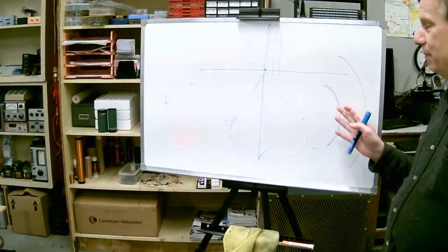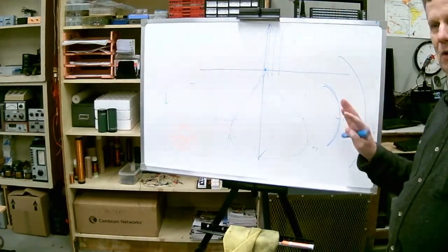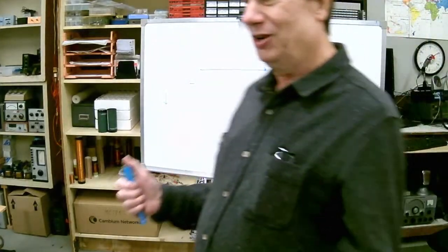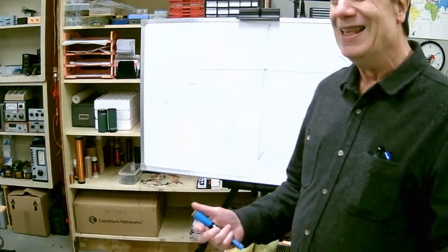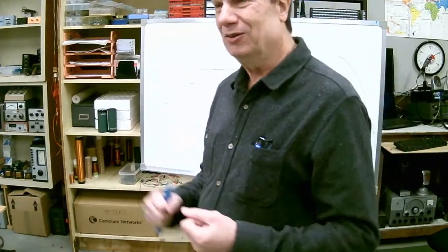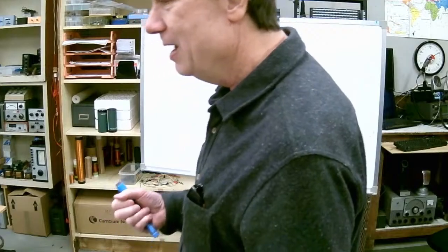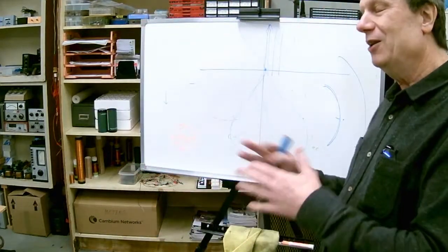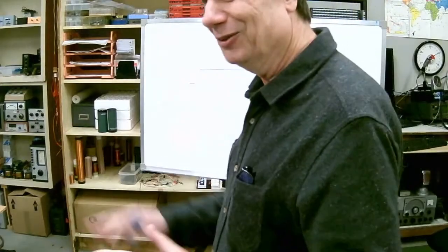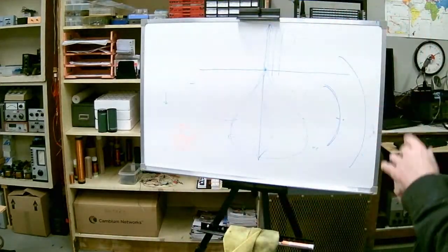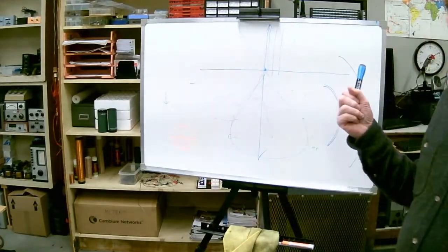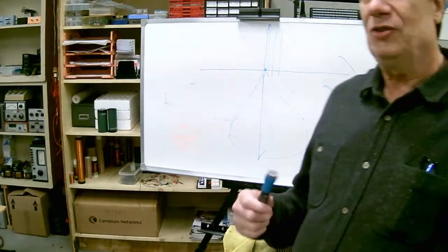Because I have a good analogy of almost any antenna: you take a beanbag chair, which has the same surface area, and you can punch a bunch of different shapes and reorient the direction of the signal, but the total radiated signal is always going to be proportional to the surface area of the beanbag chair. You've got a certain amount of leather out there. But it's always going to attenuate with distance. So the farther we get away, we're going to have an attenuation, and that's with no losses whatsoever.